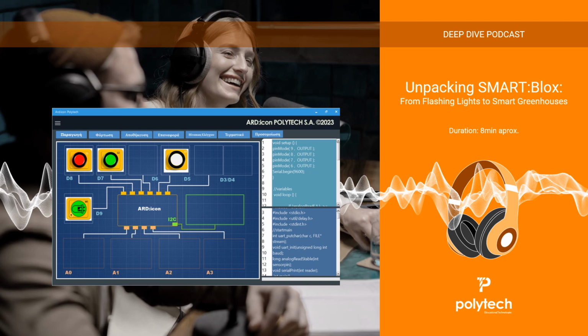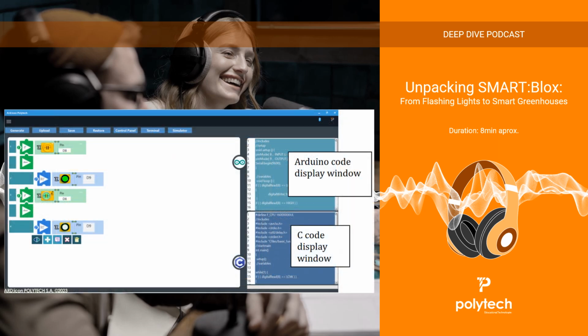Okay, so the documents kick things off with a guide to their programming tables. It looks like there are 4 columns. Yeah, 4 main columns to help structure the programming in their visual software, R.icon. First one's indentation. Now, is this just formatting? Well, it looks like formatting, but it's actually functional. It shows the code structure. You have to start at the first indentation level, and the software helps you move in and out to nest commands, like putting actions inside an if statement. It's about logic flow. So it dictates where in the sequence or logic a command sits.